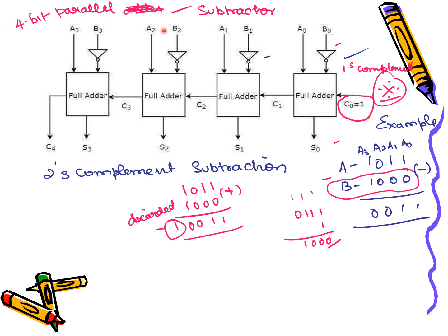So this is a 4-bit parallel subtractor block diagram. Here only two things have to be modified. What is that? I need the circuit to perform two's complement in addition. Two's complement is done first using an inversion operation, and then we add a 1, or the high input signal, at the LSB, that is the initial stage.